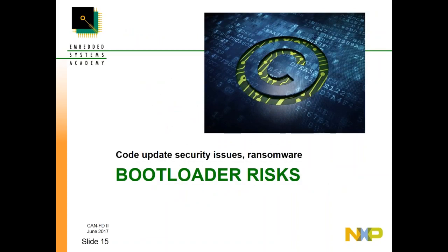We also should review bootloader risks. In the past, CANopen bootloaders would typically only have minimal security protections. Often the protections would be so minimal that even a record and replay attack could succeed. If you were able to record the traffic communicated to activate a bootloader, to erase the flash, and to transmit the code, you could just replay the recorded host messages, and that would work, and you could update other devices this way. The idea in CAN and CANopen systems for a long time was that these are private, locked systems where attackers do not have immediate access, that networks are deeply embedded in some